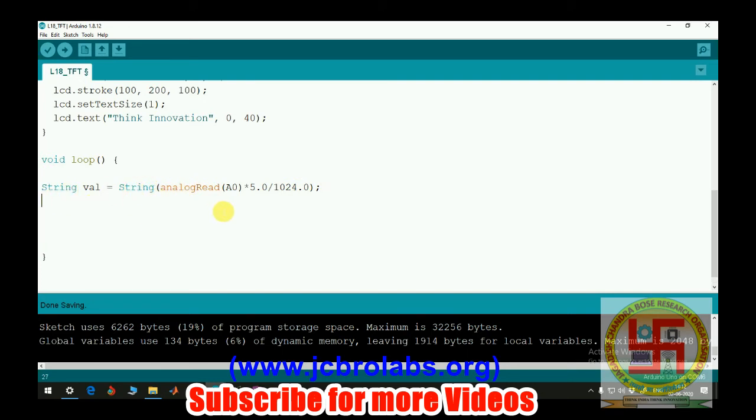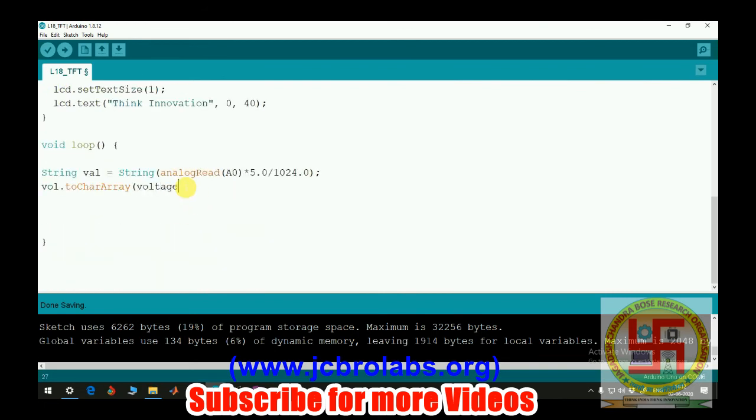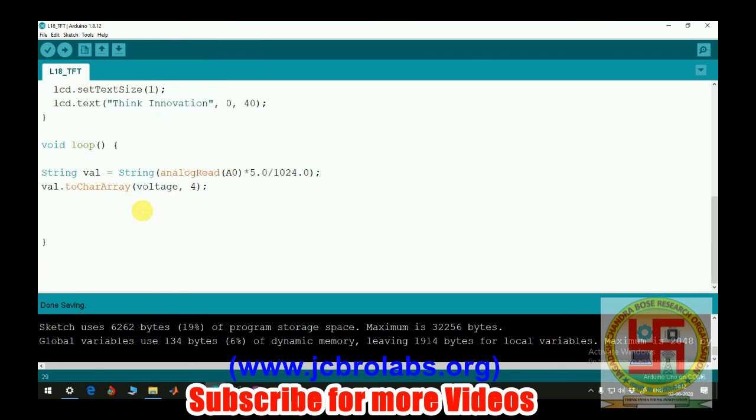Now we need to convert this string to a character array. For that we type voltage dot toCharArray. In this we will take the voltage variable which we have created, voltage comma 4. So what will this do? This will convert this string value into a voltage character array, and that character array will be stored into this voltage variable which we created here. Now we'll simply display it.